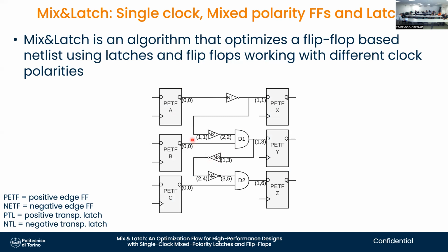And here we have an example of a very simple logic with a bunch of flip-flops at the input, a bunch of flip-flops at the output, and several paths of different lengths between the flops of the launching stage and the capturing stage. You see that I have a very short path here, and a very long path here, and another short path here, and another short path here. You can say, well, this is contrived. No, this is just a full adder. This is an n-bit adder circuit, ultra simplified, but this is what adder circuits look like in practice. Multipliers are pretty much the same thing. So this is not a rare case. This is the common case.